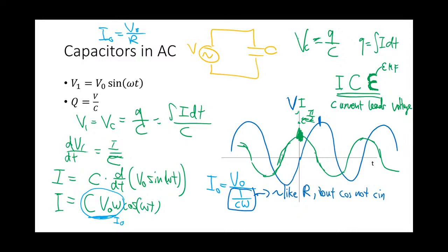We call it reactance, and we use the symbol X. That's where reactance comes in. It's when you have a component that changes the AC from a sine to a cosine. But if we're still interested in just how the amplitude gets affected, we can use this reactance number, very similar to how we would use the resistance number.